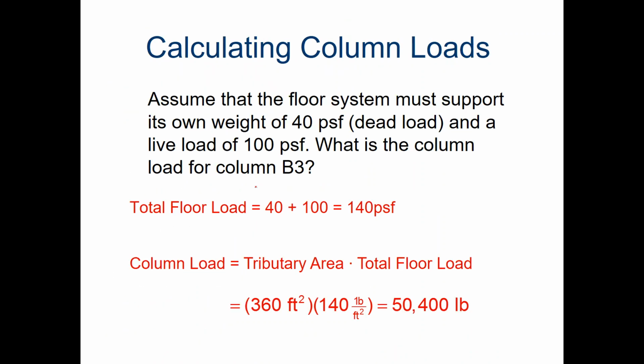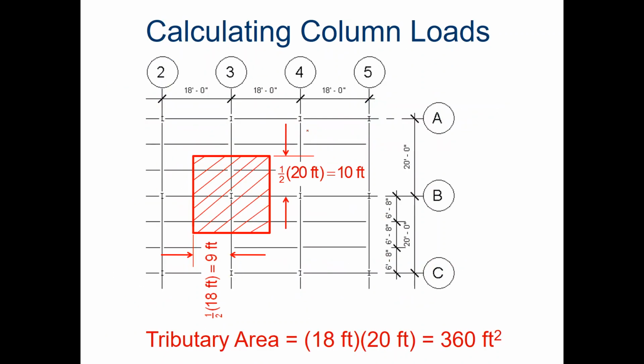And I don't believe this PowerPoint goes on. I'd just like to explain to you how to calculate the tributary area of, let's say, a corner column. So this column here, if you want the tributary area of that, it's just going to be half of the distance to the next column in both directions. And so it's actually going to be a quarter of the tributary area of one of the interior columns.